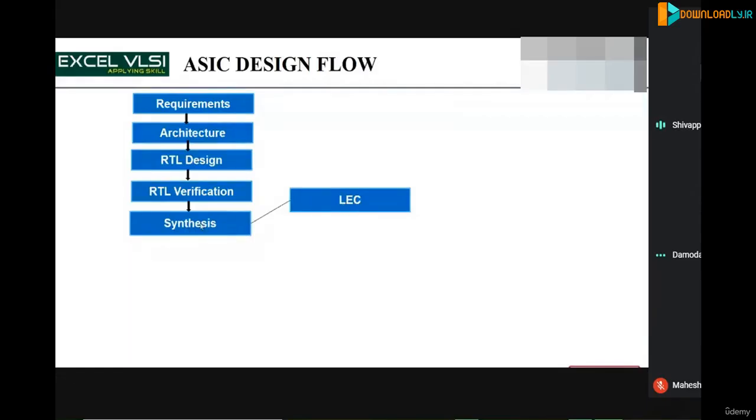Once you synthesize, the Verilog code is converted to gates, and then you have to check that the gates you got through the synthesis process are equivalent to the RTL you have written. That is LEC, logic equivalence check. And then the DFT process, that is the design for testability process.